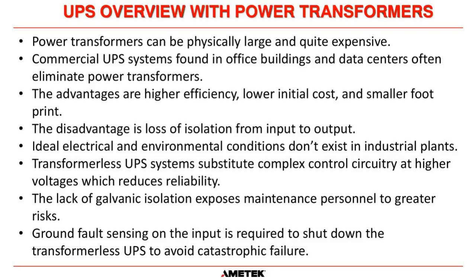Lack of galvanic isolation exposes maintenance personnel to greater risks. Typical ground fault sensing is required to shut down the transformerless UPS to make sure it cannot backfeed the bus if there's a ground fault in the 480 distribution.